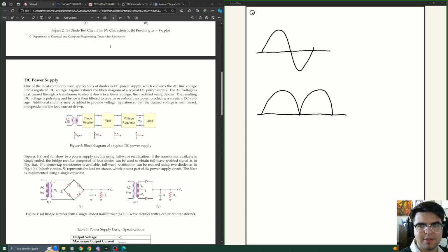And what it does is that this capacitor at the output holds on to some of this charge. There's going to be a little bit of a period here where the AC voltage is going to be pretty low. We want a consistent DC output load, so we attach a little capacitor there that's going to charge up once we're allowing voltage across, and then maintain that charge over the period where we're not outputting any voltage. So it will charge up and slowly discharge over the band. And then we'll be allowed to connect again, and then we'll slowly discharge again.